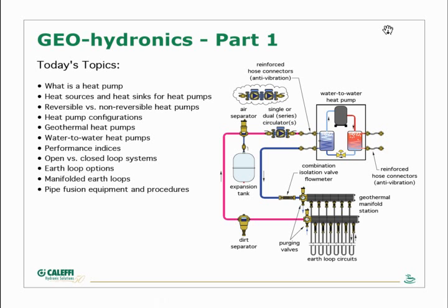The heat pump's performance is very much determined by the water temperature that the distribution system operates at, as well as the water temperature of the earth loop. And designers need to be very cognizant of those performance characteristics.